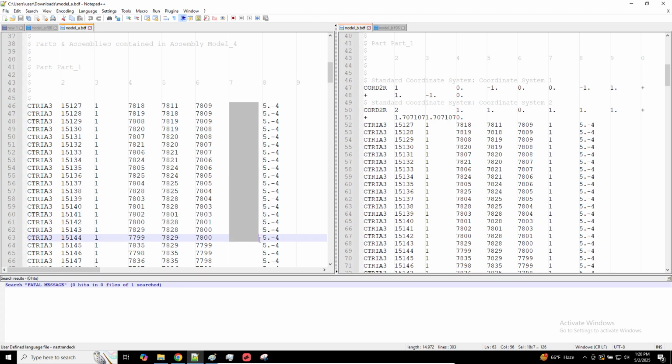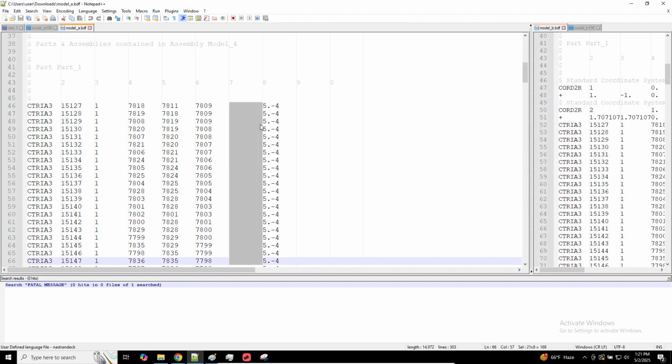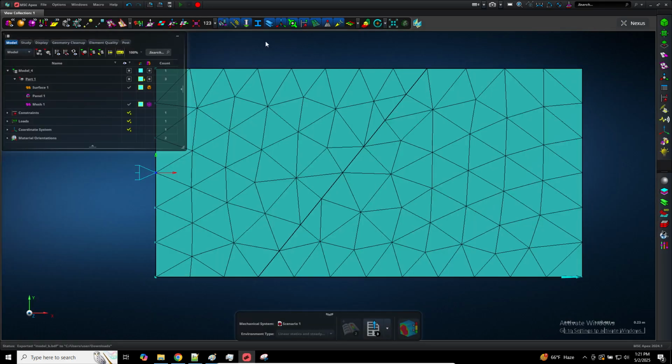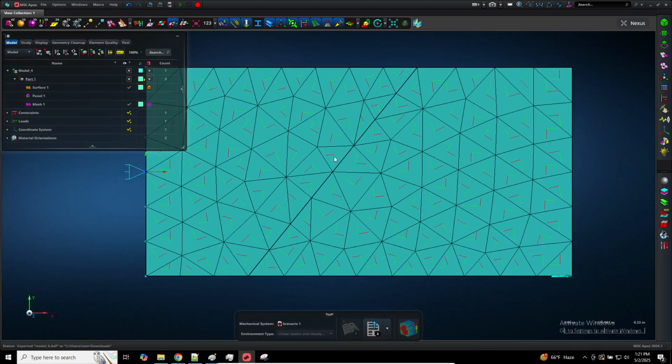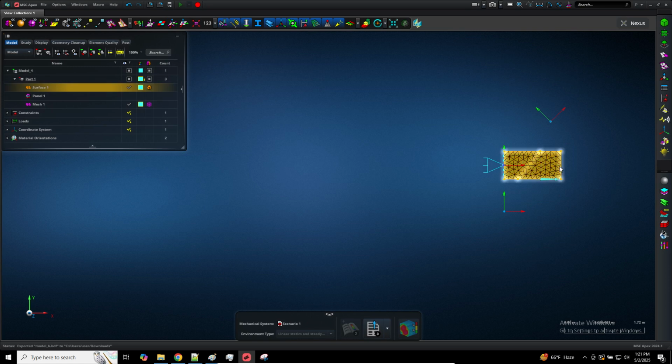So now there's one very different option here. Field 7 is by default blank. Field 7 defines how you orient the material coordinate system of that element. Before it was blank. So since it was blank, by default, the material coordinate system was parallel to the element coordinate system. So that's what we had here. But then this is what we did. We went ahead and set this.